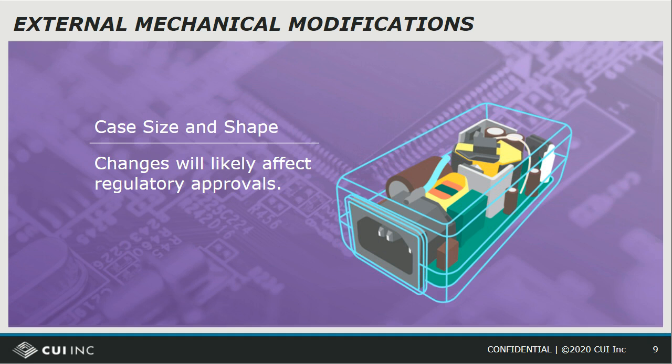We don't tend to see many modifications done to internal supplies. We see external supplies modified fairly regularly. The input voltage is normally not an issue on power supplies, in that most power supplies these days are switching topology power supplies.